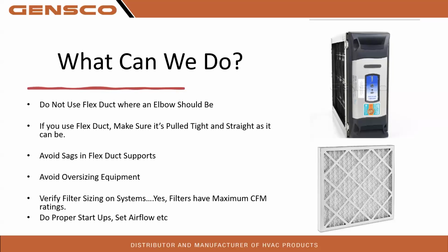So how many times do you think the air is going to have to be supplied to those back rooms to actually reduce the heat? Because like I said, we're adding or removing heat. That's all we're doing. And we can't do it if we're not moving refrigerant, if we're not moving airflow. So do not oversize equipment.